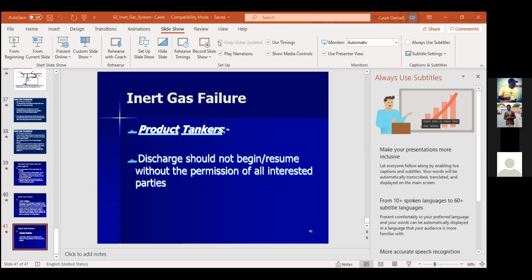So there are barges now, more like barges, that supply inert gas to ships that are going to dry dock, that don't want to run their inert gas system on completion of dry dock, and they want to go in inert atmosphere. Is it the direct inert gas they supply you, or the flue gas? No, it's inert gas, it's not flue gas. In Dubai, it's inert gas.